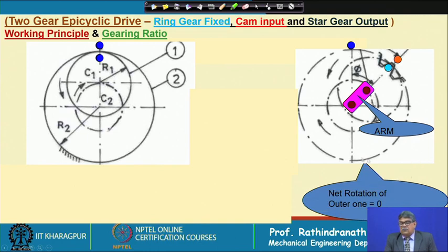The gear has no motion now, but the pinion will come to this point, where the arc from the light blue point to the dark blue point on the pinion must be equal to the arc length on the gear from the orange to the deep blue point.